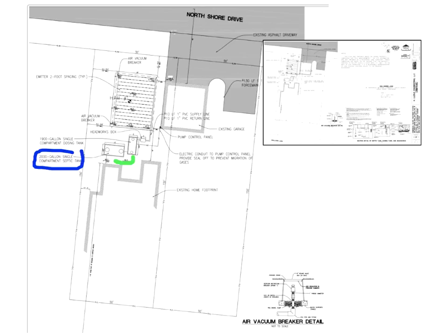As I said, it works. And that in turn is going into a headworks, which has the filter, and then out through a supply console, up and through the drip system and back down the other side. They've got air vacuum breakers here and here, so I presume the slope is going this way from the position of the air vacuum breakers.